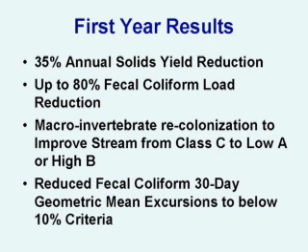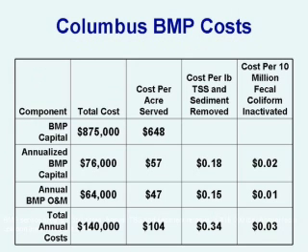And what has been so significant for this BMP is that with all these solids removal, we're removing annually about 35% of the annual solids yield, and that has improved the downstream fine sediments in the substrate of the streams. And right away, the people doing the aquatic biology surveys have observed that the substrates are much better, and in fact, the macroinvertebrate community was found in some places to be as high as 600% improvement in the numbers of the species of macroinvertebrates, enough to change it from, say, a Class C stream to a low A or a high B stream.